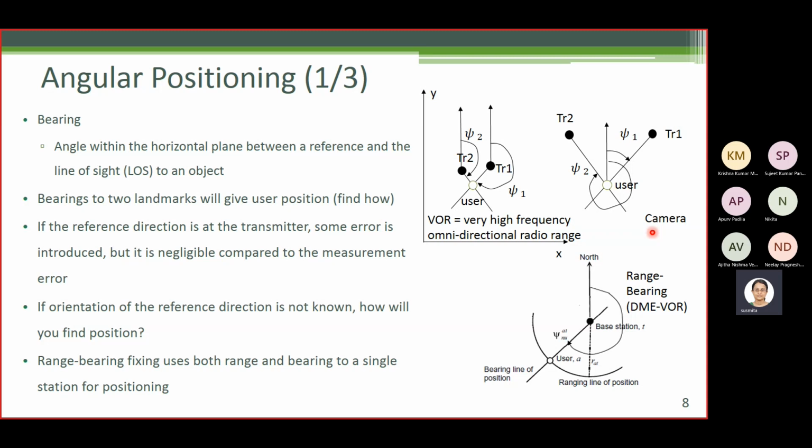Then the camera can calculate the round trip time. It knows when it transmitted the pulse, and it can also note the time when it receives the reflection. So it can calculate the round trip time, just like DME, of the transmitted pulse from a particular feature. So this will allow the laser camera to determine the range to that feature.